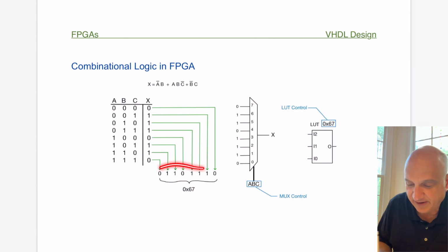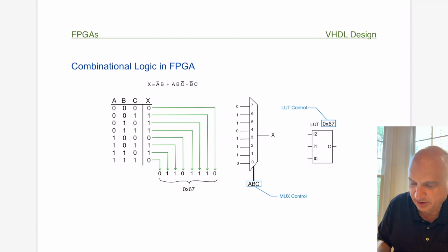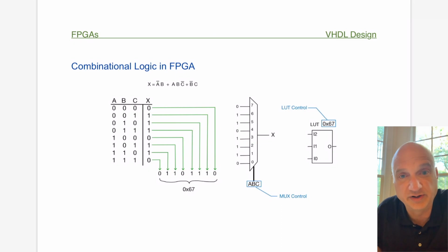So now this is the value that gets programmed over here. And then what we've done is we said, all right, bit 0 goes into the 0 position. Bit 1 goes to 1, and so on until we get to bit 5, which would go to bit 5 input, and then bit 7, of course, would go to bit 7 input. And that's how we would write it in here. Now, we can represent this value as a hex value by converting the binary value here into its hex equivalent, and then applying that value to the LUT as a value you would program into the LUT. So when you do a VHDL expression and you create a Boolean expression and you're assigning a value of x to this equation, it's basically going through and analyzing and creating this constant value here and programming it into the LUT of choice to give it that functionality.